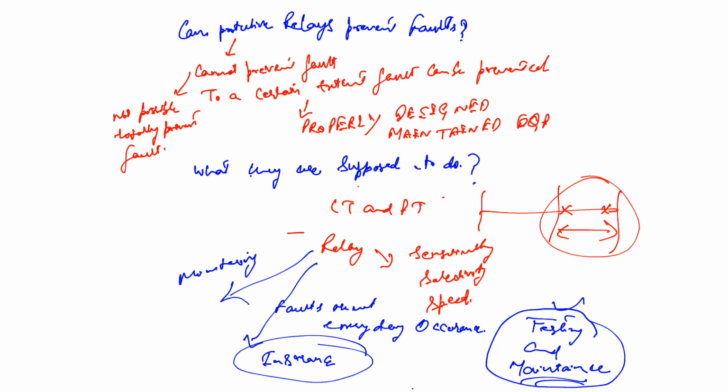So this is all about this lecture. Today we have discussed some part of the shunt fault, and the characteristics we have to take into consideration while seeing whether a fault has occurred or not. In that case we see an increase in the current and a substantial decrease in the voltage. And we can use these characteristics for designing the system in such a way that it can detect the fault.